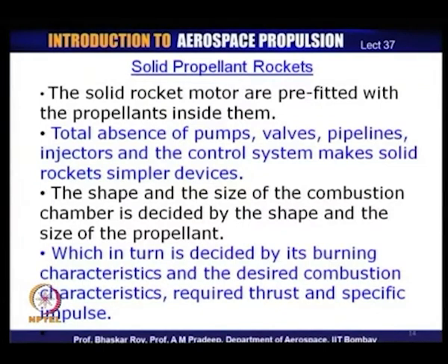And this is a solid which has a shape, which has a size, and all this is housed or prefitted inside the combustion chamber of the rocket. And hence, all this together decides what the combustion characteristics is going to be, what the burning rate is going to be, and what is the time during which we will have the rocket operational.